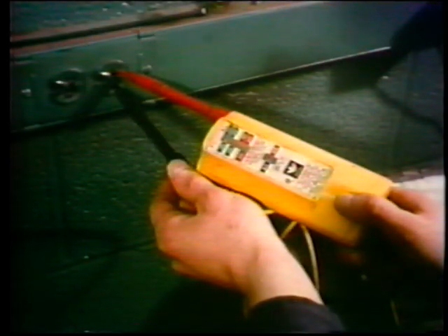But before he is certain that the controller is de-energized and can be worked on safely, he once again tests the voltage tester with a known power supply. This test verifies that the voltage tester is operating correctly and that his readings were accurate.